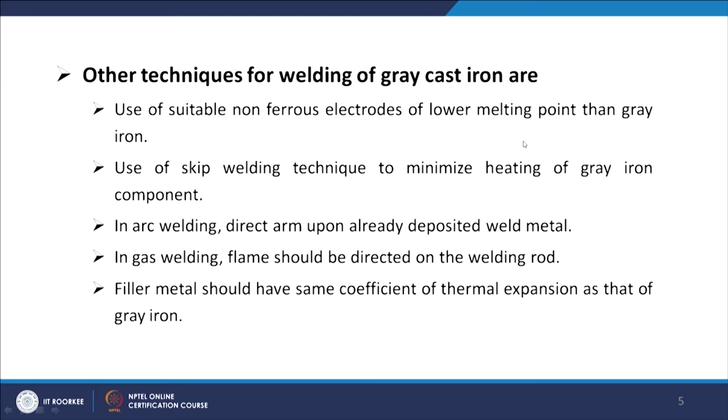Then the filler metal which you are employing also plays a very important role, and it should have the same coefficient of thermal expansion as that of the gray cast iron. So, whatever filler metal you are choosing, it must have the same type of thermal expansion as that of the gray cast iron. In that case the undesirable effect will be minimum.